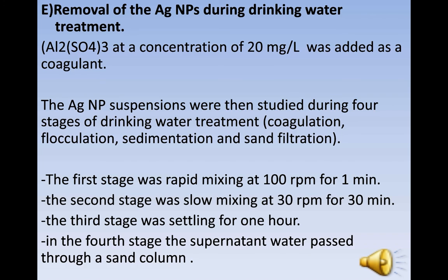coagulation, flocculation, sedimentation and sand filtration. The first stage was rapid mixing at 100 rounds per minute for 1 minute. Second stage was slow mixing at 30 rounds per minute for 30 minutes. The third stage was settling for 1 hour. In the fourth stage the supernatant water passed through a sand column.